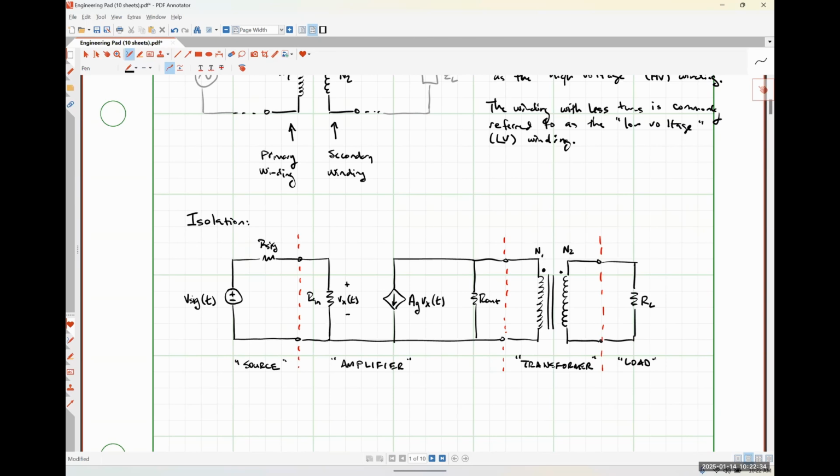Now, there's no way for you guys to particularly know this because you don't have a particularly rigorous, or to my knowledge, any background in power electronics or anything like that. But typically speaking, the output resistance of a transistor-based amplifier, so a solid-state amplifier, is going to be fairly large. So hundreds to thousands of ohms. And so if those two things are directly connected together, we have an issue because something large in parallel with something small is going to look like effectively something small. And so practically no power is actually getting delivered to the speaker.